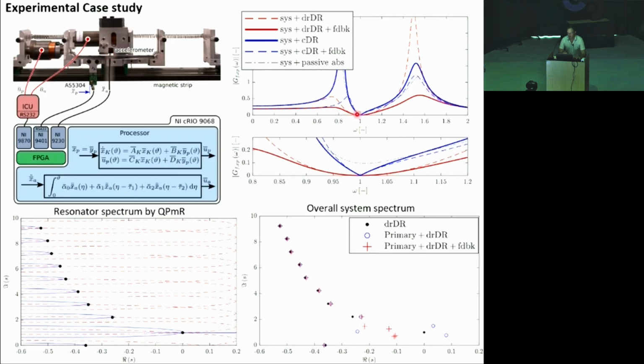From the transmissibility, you can see that we got lower sensitivity. The red one is for a double root, the blue one is for a single root at the imaginary axis. Also in the spectrum, you can see that it is a double root because we have an intersection of two curves representing the zero isolines of the real and imaginary parts of the characteristic function.